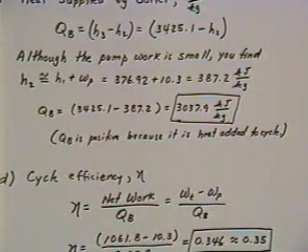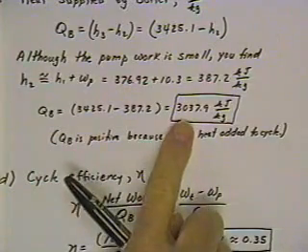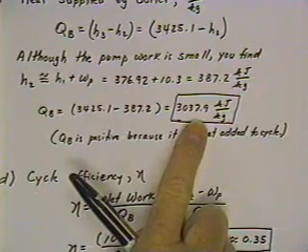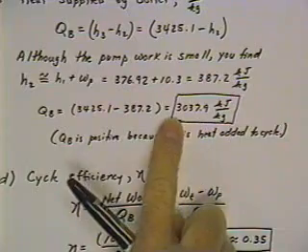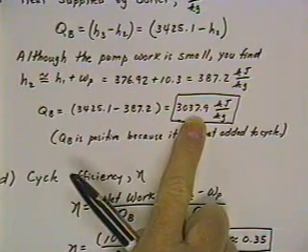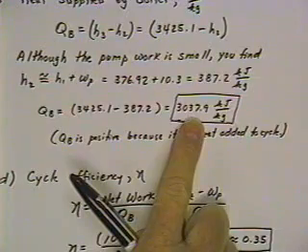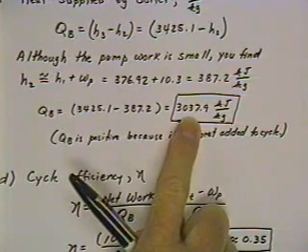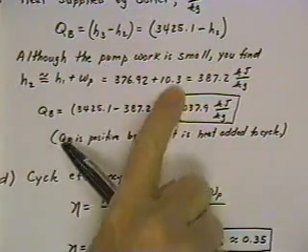the pump. The only problem is that you would likely find one of the answers on the exam to be 3047 or roughly 3048 in there, because it would be what is called a distractor, and it would be a very common mistake to ignore the work of the pump. And so anytime that you find two answers that are real close together, you have to be real suspicious on the exam, because one of them is likely to be right and one of them is likely to be wrong by ignoring something like the pump work here.